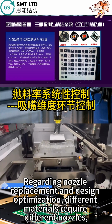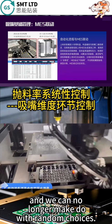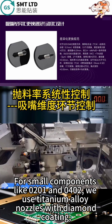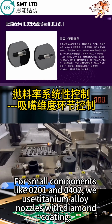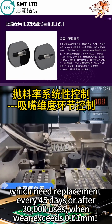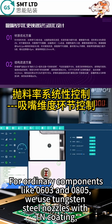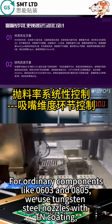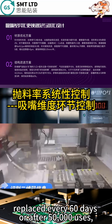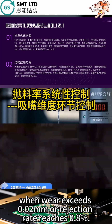Regarding nozzle replacement and design optimization, different materials require different nozzles, and we can no longer make do with random choices. For small components like 0201 and 01005, we use titanium alloy nozzles with diamond coating, which need replacement every 45 days or after 30,000 uses, or when wear exceeds 0.01 mm. For ordinary components like 0603 and 0805, we use tungsten steel nozzles with TiN coating. Replace every 60 days or after 50,000 uses, when wear exceeds 0.02 mm or rejection rate reaches 8%.